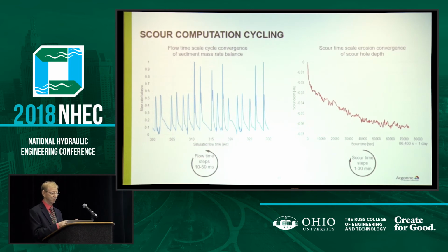So basically, these two plots are showing you each side in terms of convergence. The CFD side is going through many cycles. We cut the entire computation up into about 200 steps or so. So you get the expected scour depth, you could do that by using HEC 18, and then you just divide that depth by 200 to get a target displacement for one cycle. And then that's a parameter in the program that deforms the bed.